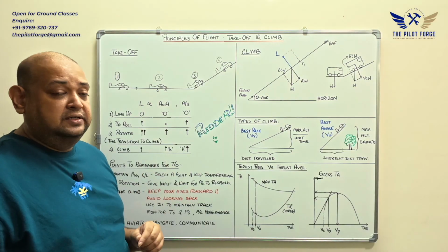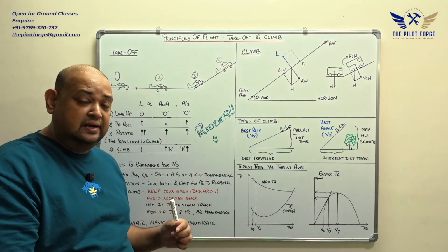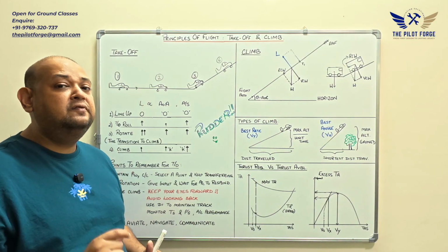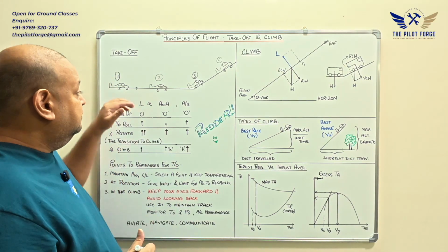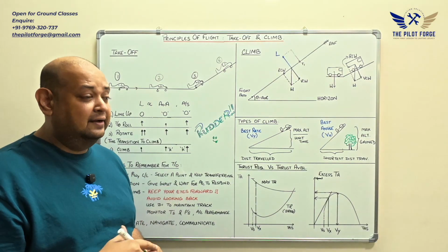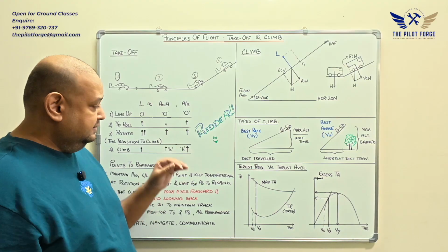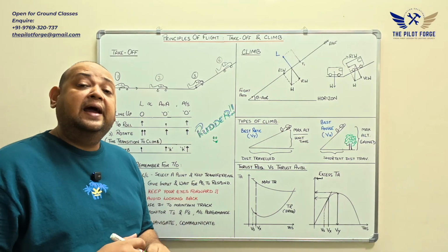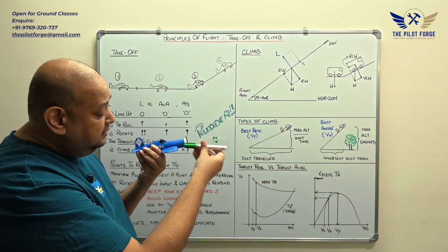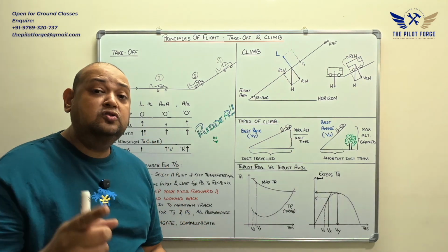So in this situation, what you need to remember is that the way the wing is attached to the aircraft, it creates a slight positive angle of incidence. Now this positive angle of incidence also helps with the angle of attack. But since it is not moving, airspeed is registering as 0, therefore angle of attack also is 0. When the wind that is interacting with the aeroplane is strong enough, the angle of attack also becomes effective.